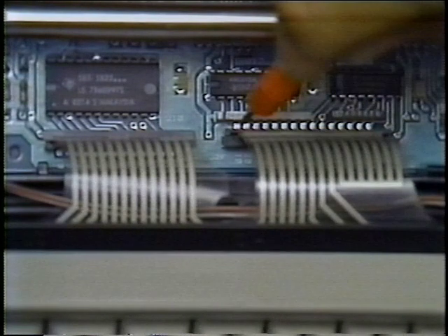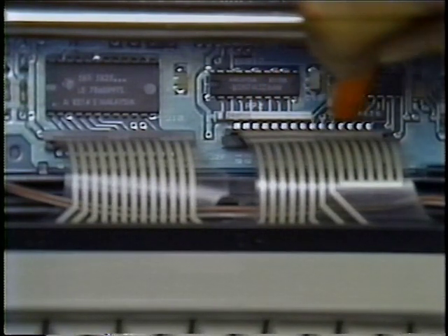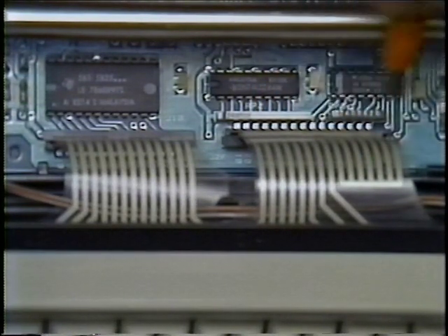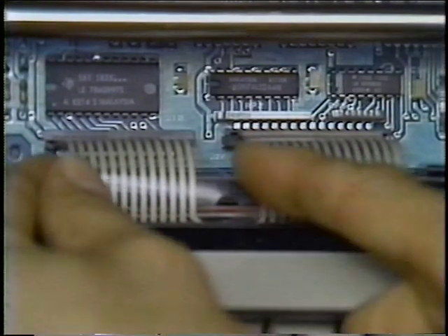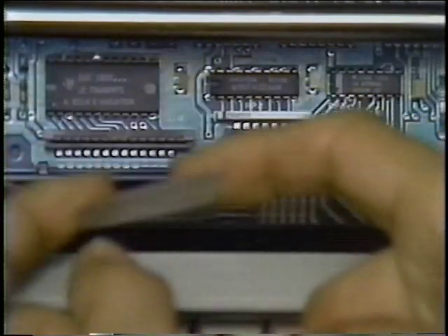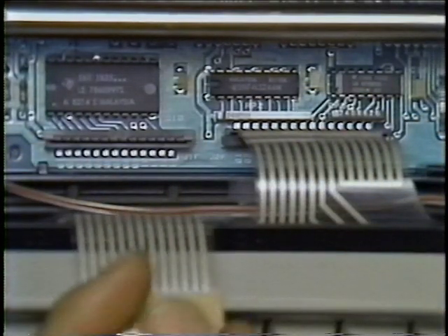These function boards will also have probe points for connectors J1F and J2F. When taking meter readings on these boards, use the probe points to prevent damage to the connectors.